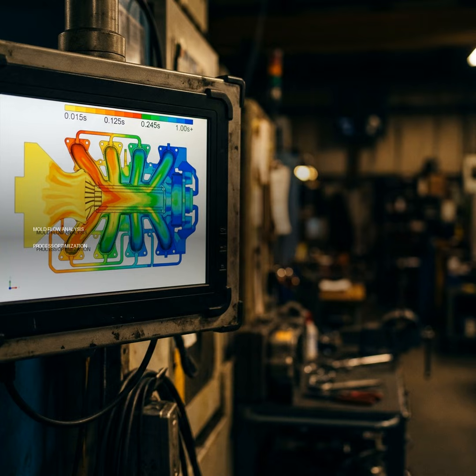And shrinkage too. I imagine that's always a challenge with plastics. Oh yeah, volumetric shrinkage, or shrinkage volume, is key. It's the reduction in part volume from holding pressure and cooling. You want that shrinkage to be as uniform as possible throughout the cavity. If it's not, you adjust the holding curve to enhance uniformity.